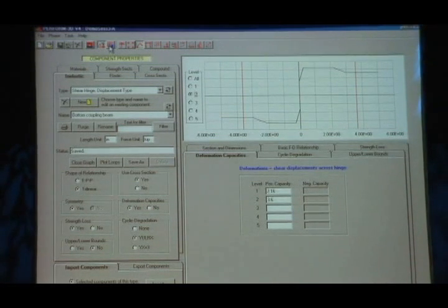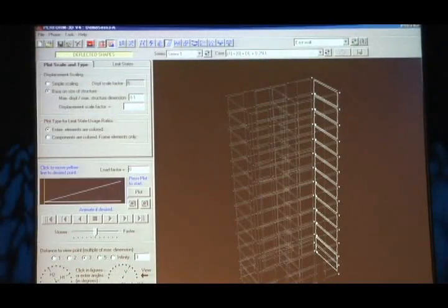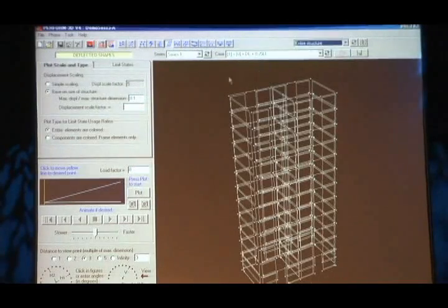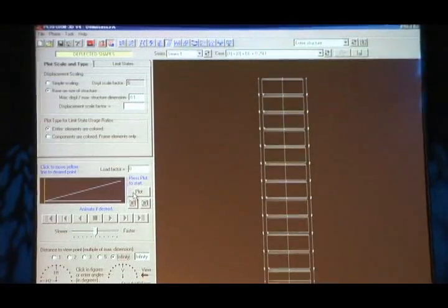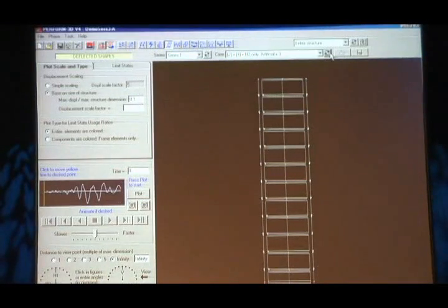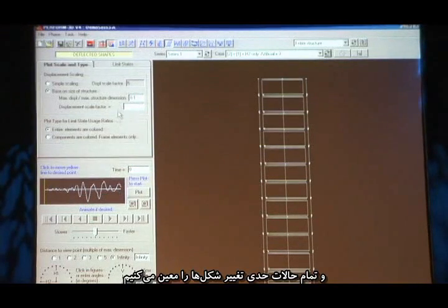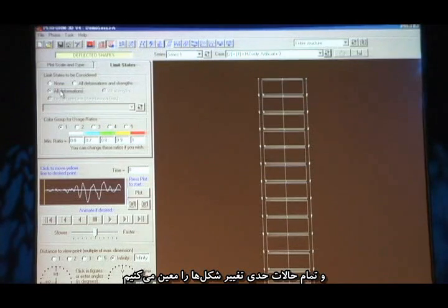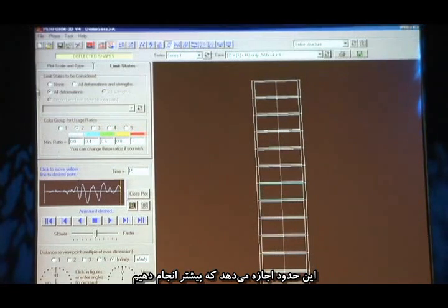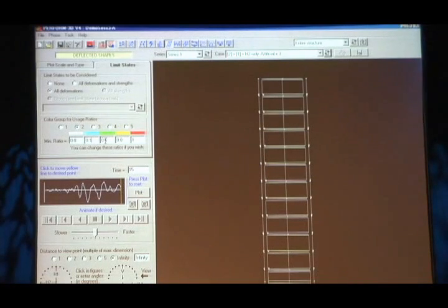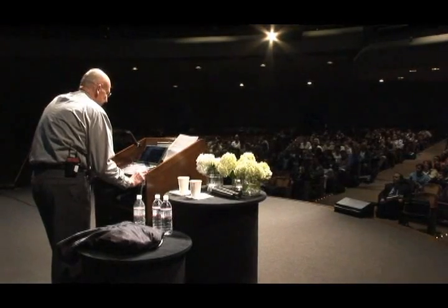And if we look at it in view, we're going to do an earthquake. Okay. This thumbnail is what is happening with the earthquake, and I'm going to set up all of the deformation limit states. It's doing rather a lot of calculation here. At the end, let me do a little bit more here so we can make this one show up a little bit more. It's really quite strong. So I'll make that 0.1, 0.2, 0.3 and 0.4.